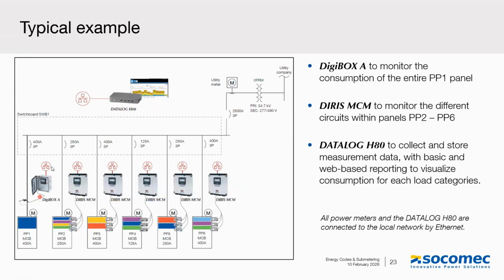All those meters are connected over the local network, so it's an Ethernet cable connected to the local network. And then it's a matter of the data acquisition system. One of the companies that were mentioned provides energy management software that can read the measurements through Modbus or BACnet and integrate the measurements into their platform, into their dashboards.